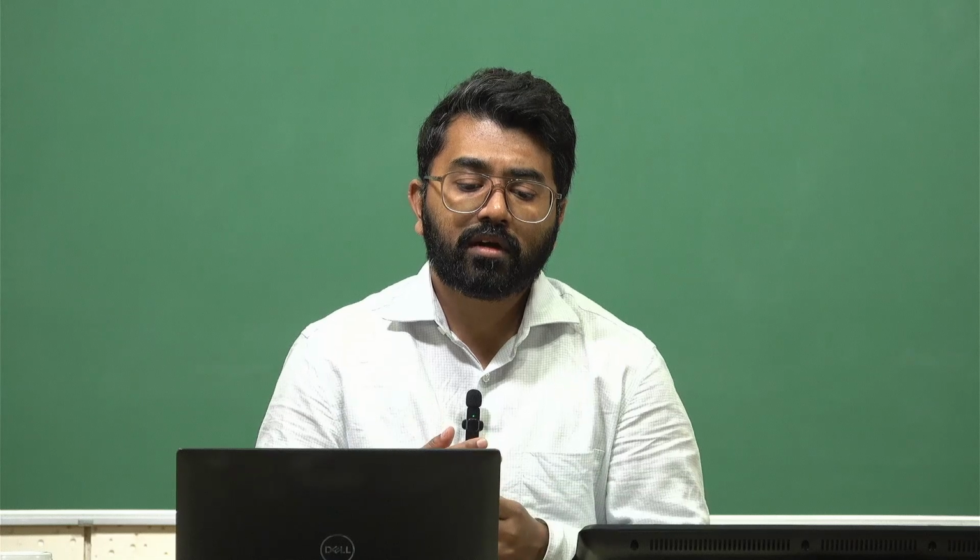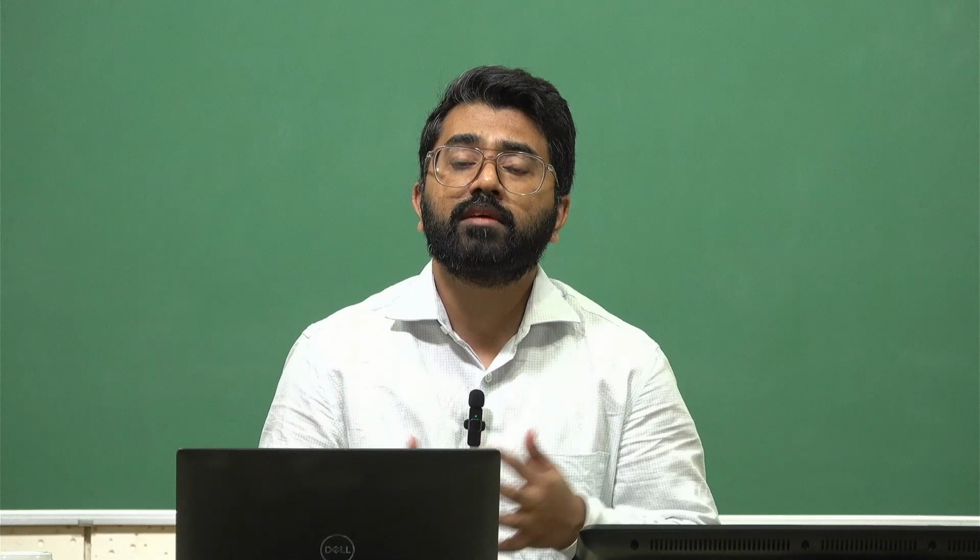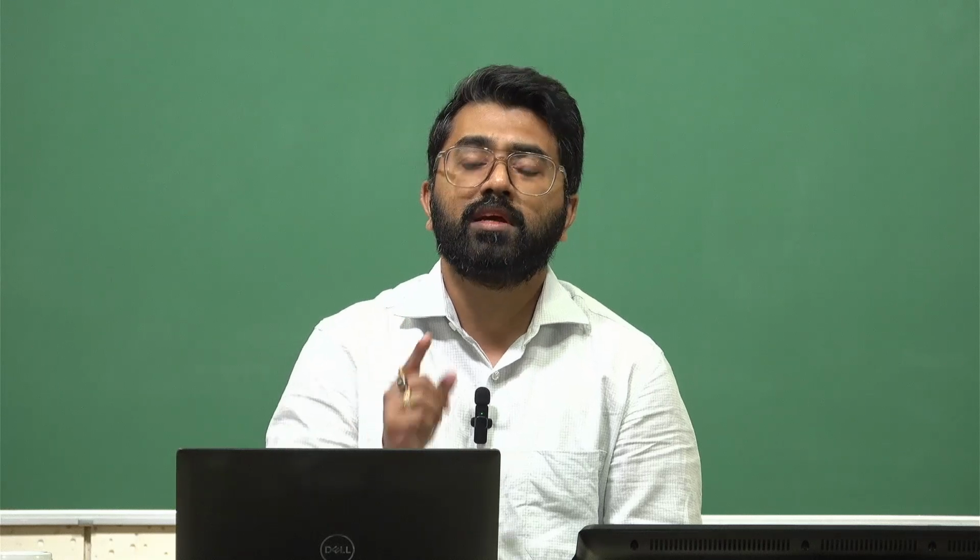Also, we looked at the total displacement sum, and this will give us a holistic view of internal stresses, strains, as well as internal displacements, which we cannot see in the experiments. So this is the first key lesson of ANSYS, where we have done one simulation considering a soft tissue but with linear properties. We are going to slowly take baby steps in the upcoming sessions, where we are going to learn and pick it up from this model.